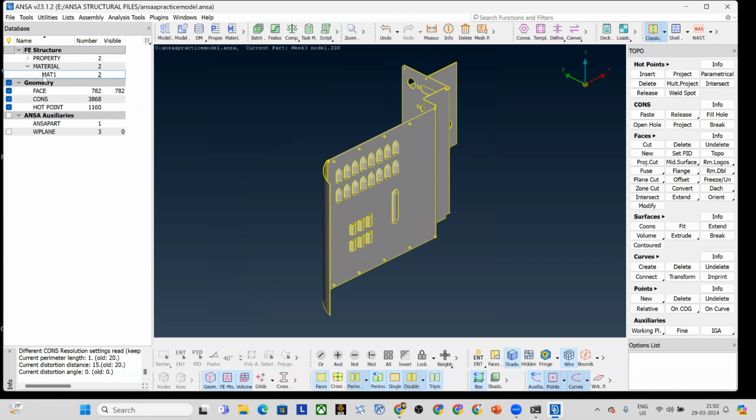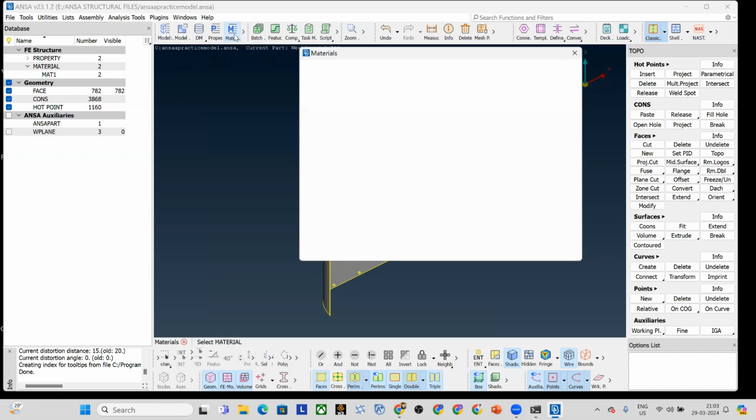And this has also been followed in the Nastran deck, and the same syntax word has been used here also. You can either double click this Mat1 material, or you can use this material tool button in your list option. You can make use of any one of these to check what material has been assigned. So this is a prime duty actually.